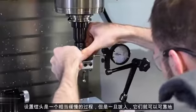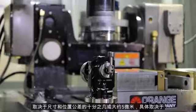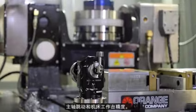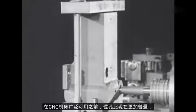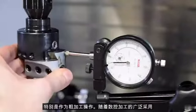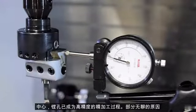Setting up boring heads is a fairly slow process, but once they're dialed in, they can reliably hold size and location tolerances of a few tenths, or around 5 microns, depending on the spindle runout and machine table accuracy. Before CNC machines became widely available, boring was much more common than it is now, especially as a rough machining operation. With the widespread adoption of CNC machining centers, boring has become more of a high-precision finishing process.